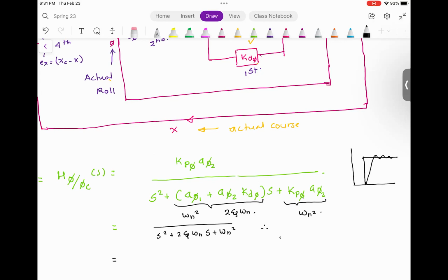You should be observing some dynamics, something similar to this in your simulation. The only way to check if your simulation is working well or not is to set the wind equal to 0. This is a test case that you can run. Set wind equal to 0, which means no wind input. Set a constant value of thrust, not a very high value, just about 0.5. And add a very small value of angle of attack or pitch. Add a small value of pitch.